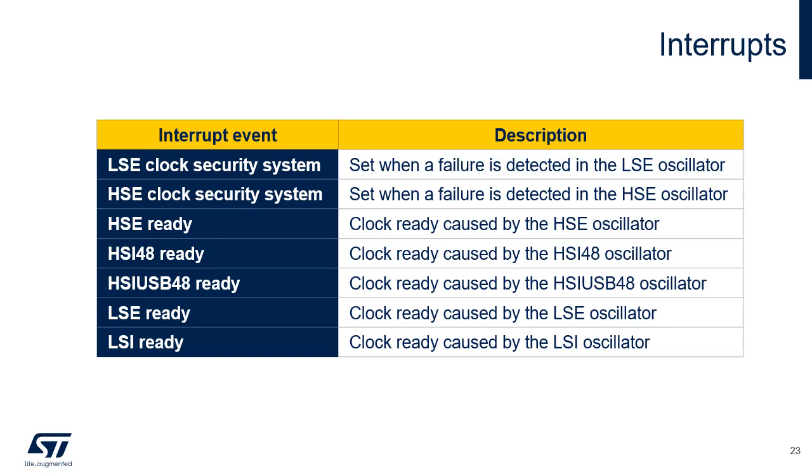This slide lists RCC-related interrupts. Both the LSE and HSE clock security systems, as well as all oscillator-ready signals, can trigger an interrupt. The flag indicating an automatic clock switch due to LSE or HSE loss must be cleared in the NMI interrupt service routine.